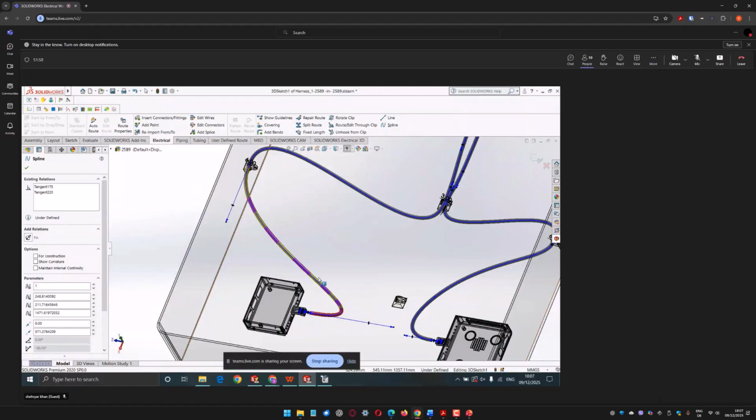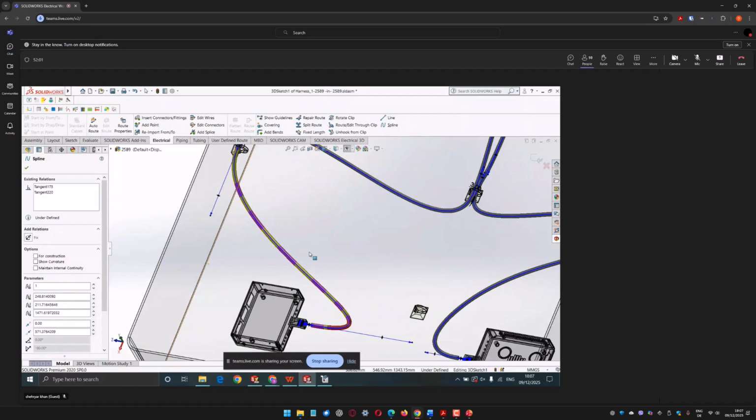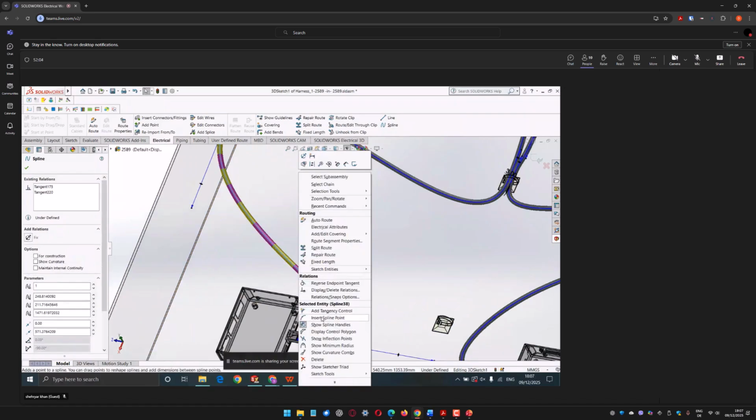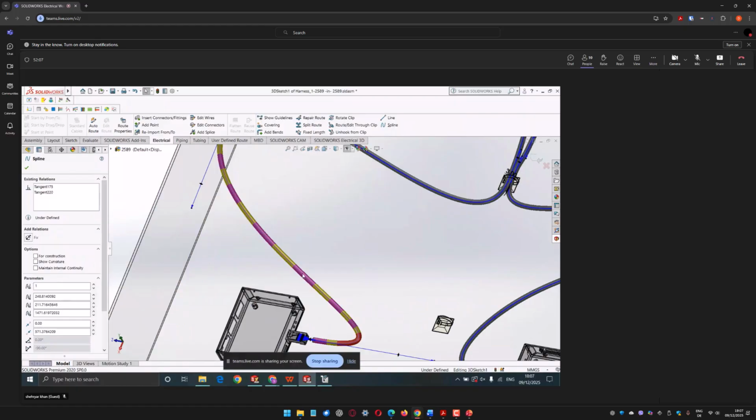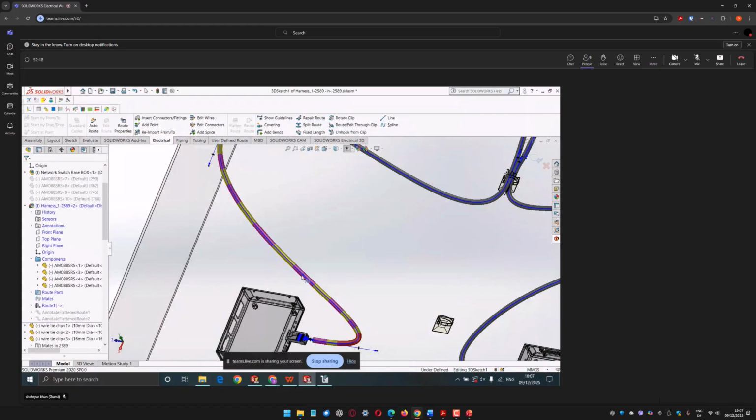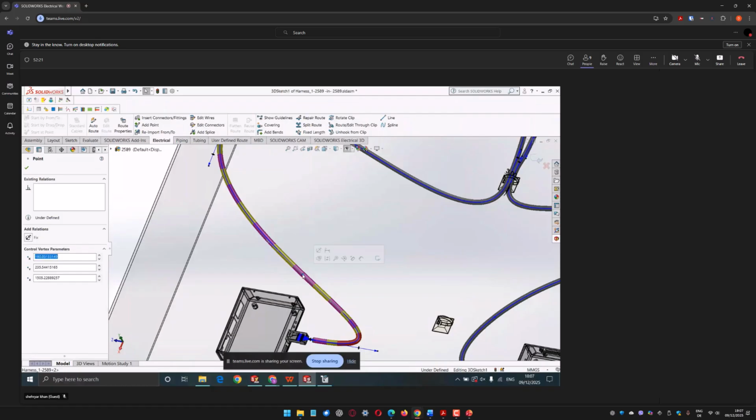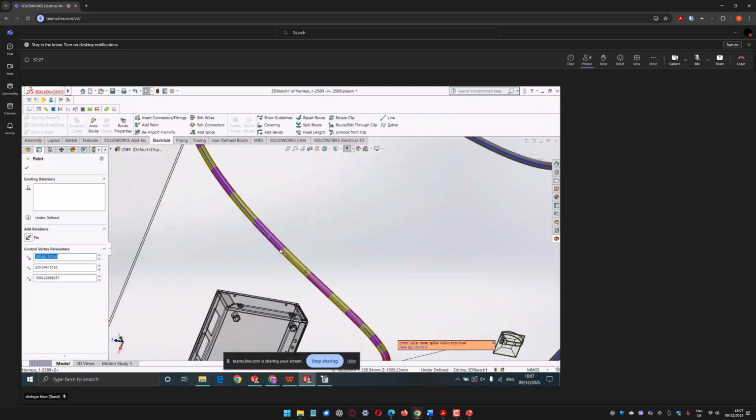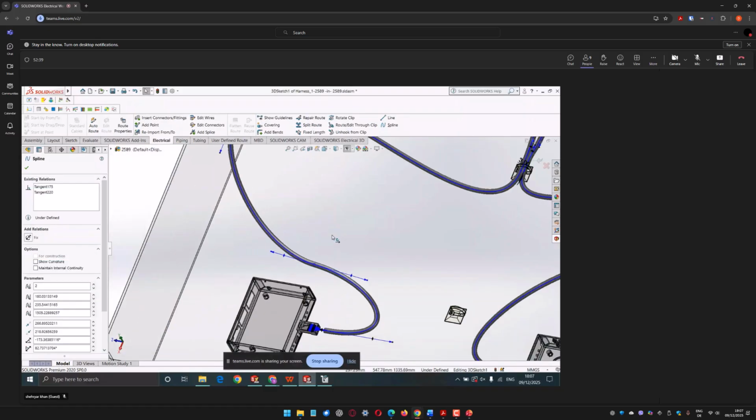Yeah, I can just create a point somewhere on this cable. So I'm taking a bit more time, just 5-10 minutes more, and then we'll be wrapping it up. There is my spline point. Now it gives me the spline axis, which I can use to move my cable in different directions. Yeah, now it's corrected. So the error is removed.